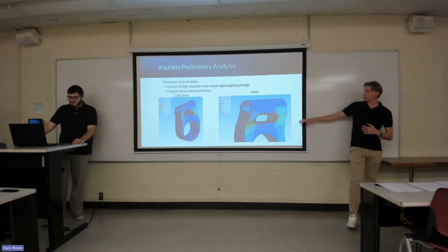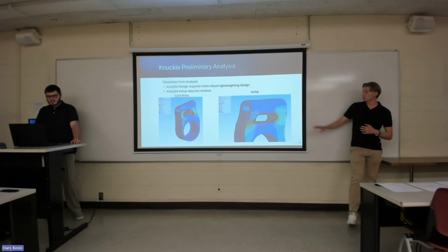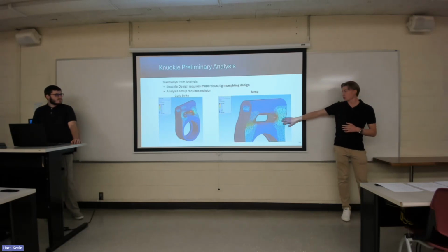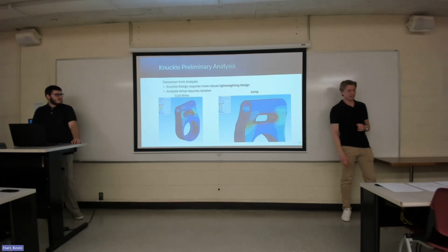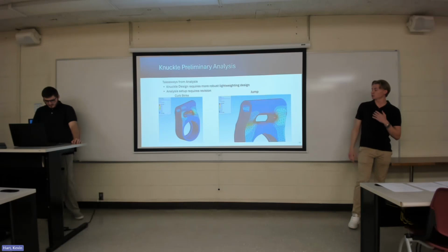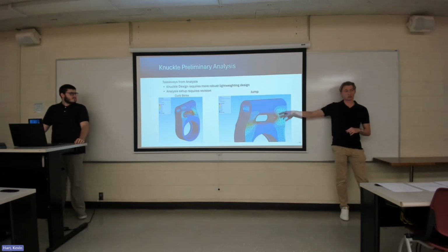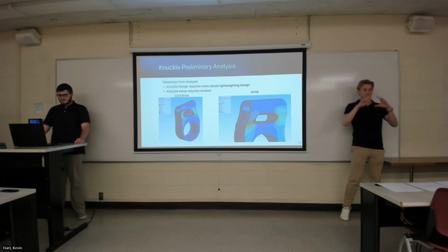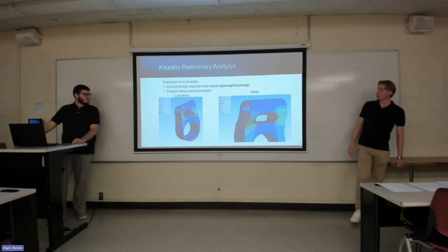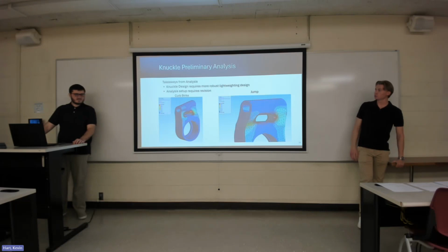Now, in terms of the jump, this one's doing a bit better, where this part isn't going to be failing in terms of maximum tensile stress. But just like with the curb strike, we're reaching peak stress around that cutout region. So that's something that we want to examine in the future.